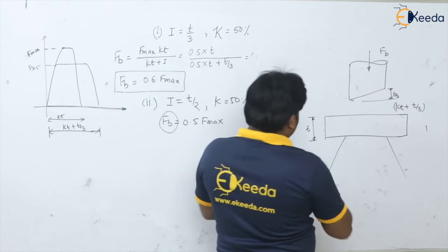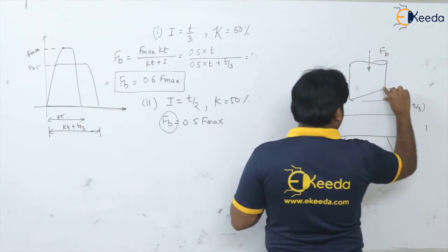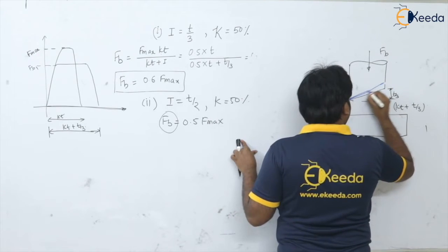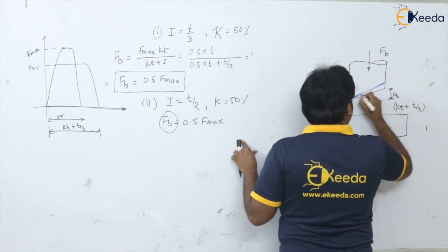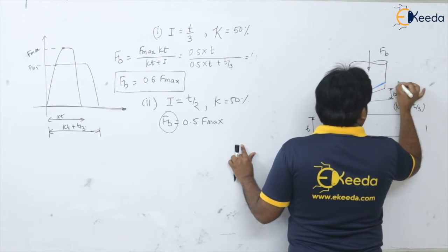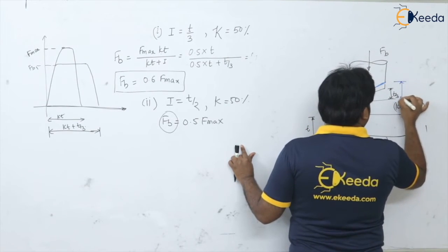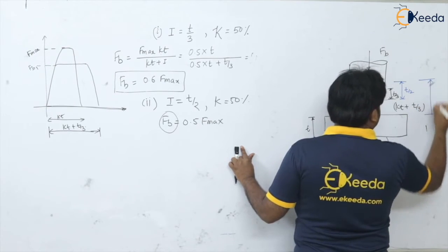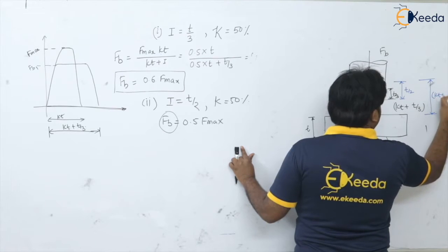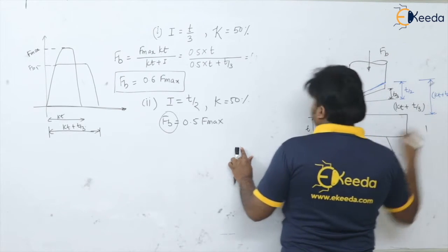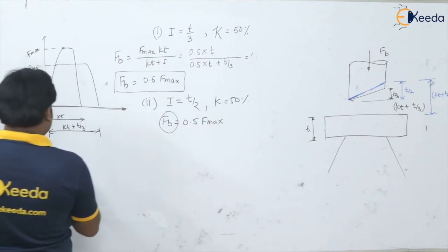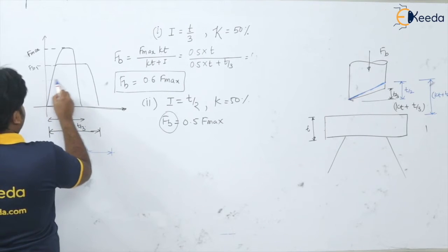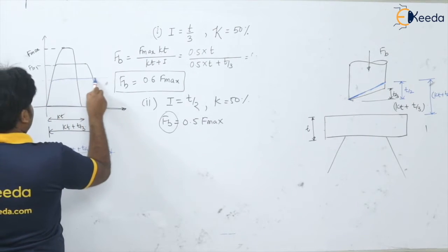Let us apply here: T by 2 means this much shear is going to be provided on the tool, that is our tool is the punch, isn't it? So this is the shear T by 2, and of course now in addition to KT, you will have this distance KT plus T by 2, and now a 50% reduction in the load.